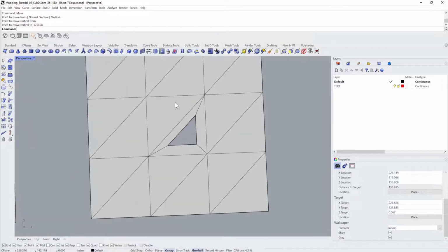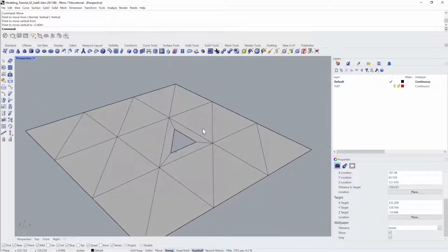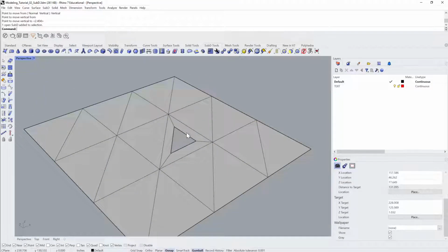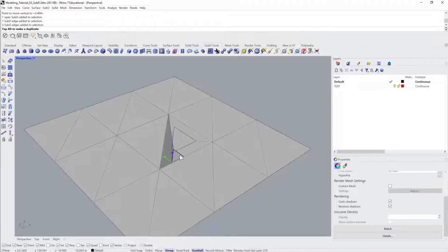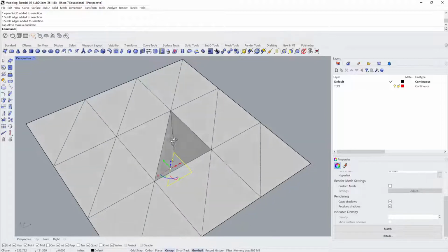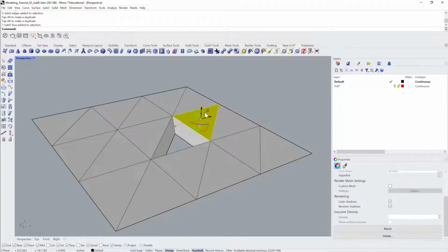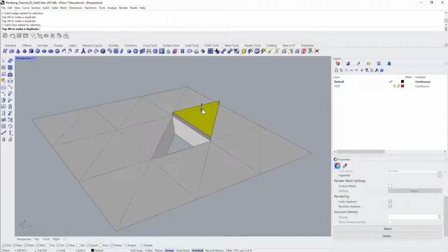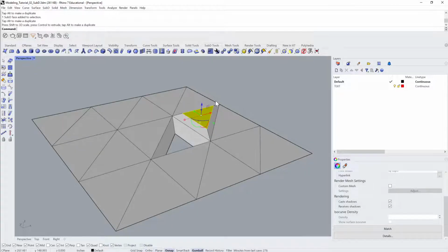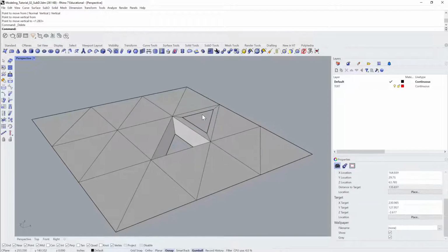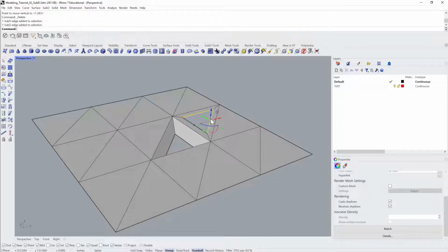So you can use the extrude actually to give yourselves things which are flat. Then of course, Shift Control, double click, and I could pull this down. I could do many of these extrusions. So let me show you how that trick works again. Move that up, Shift, scale this in, move, constrain to vertical, move that down, delete that, and now I have this opening here.